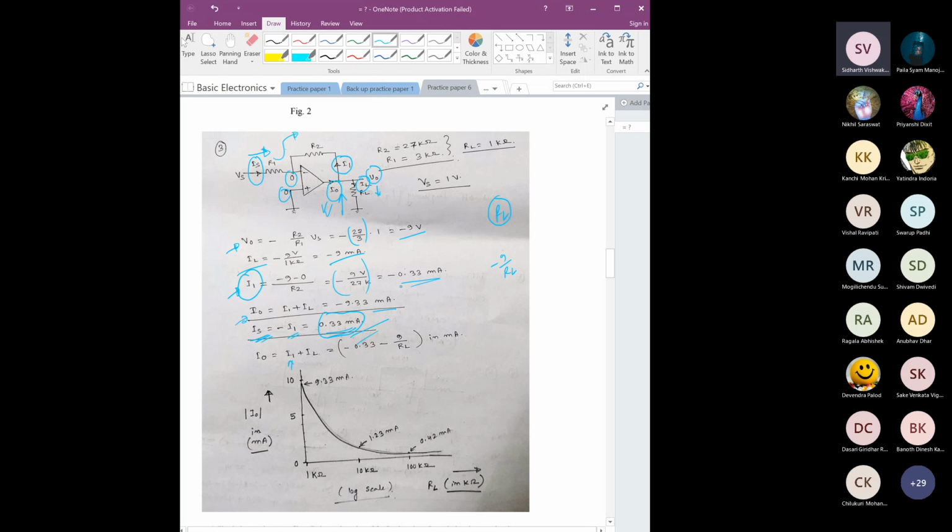So here this I1 is independent of this RL, right? But while saying that the RL value will be influencing this I1, I said RL will influence the value of I1, which is not correct. See this, are you with me in this? This V output will determine the value of this RL, and V output, for a particular range of this RL, is determined by this resistance and this source voltage, not by this resistance. So that way I1 is independent of RL.